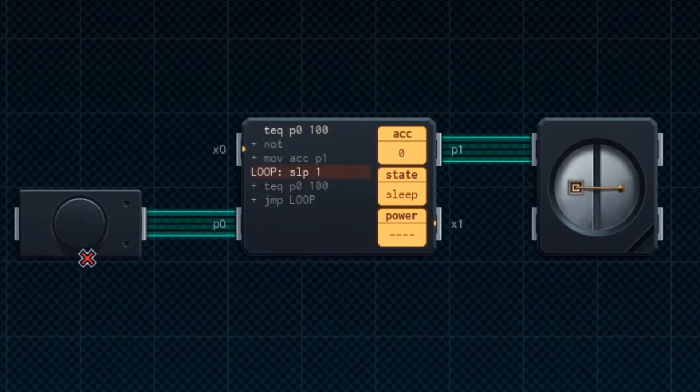So let's run the simulation, press the button, things get inverted, and yeah, this is actually acting like a proper T flip-flop. Let's hold the button. So yeah, it doesn't do anything. Let's hold the button again. Yeah, it changes only one time and it doesn't do anything. It gets trapped in the loop as expected. It doesn't execute a lot of instructions. So this is kind of power efficient as well, because most of the time it's not doing anything. So yeah, this is a very good solution, guys.